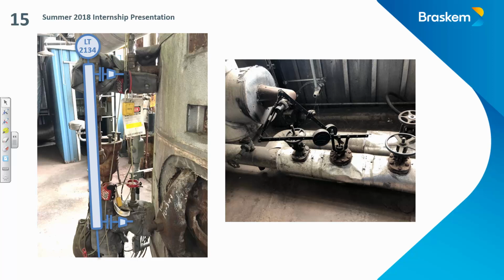A little overview of this. We have a tank, let's say GAJ, and there's a level flow down tank, so we flow down the steam condensate. If your level gets too high, which as you can see here, this thing is broken, they'll get up. So right now we're manually controlling it. It's high and low. We're losing a lot of steam. And steam's energy, and energy costs money. So when it comes down to it, we're trying to save money.